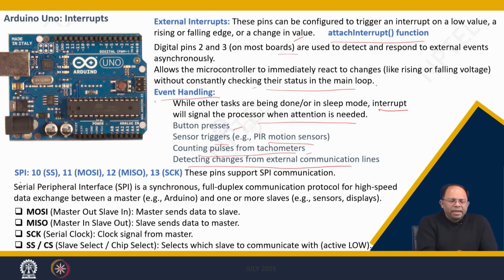Then there is SPI, this serial peripheral interface. These pins are also there, and these pins support SPI communication. This is pin number 10 SS, 11 MOSI, 12 MISO, and 13 SCK.